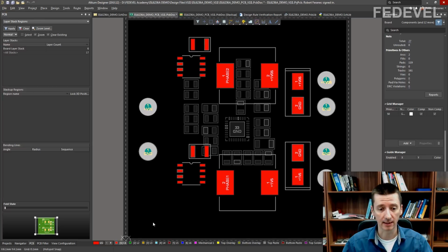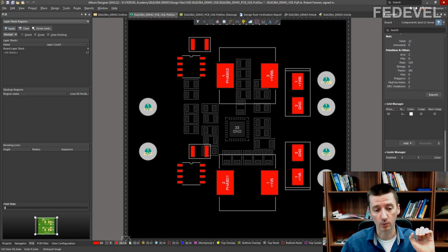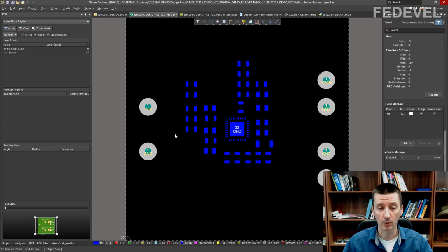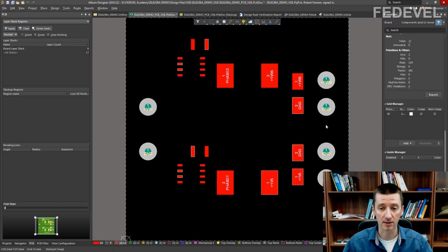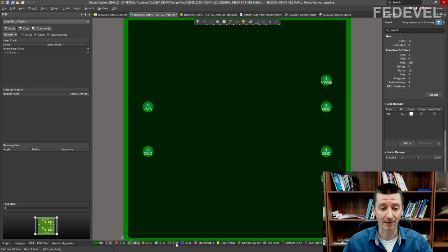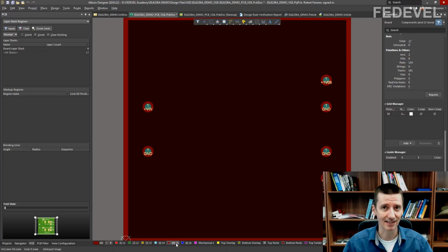Now, what you can see is the active layer, the red path on the red layer 1. All the other layers which we have here, they are grayed out. Or if you press Shift S one more time, everything will be hidden except the active layer. Yeah, if I click on layer 6, I only see what is on layer 6. Now I only see what is on layer 1. On layer 3, 4, there is nothing. And on layer 2 and layer 5, there is